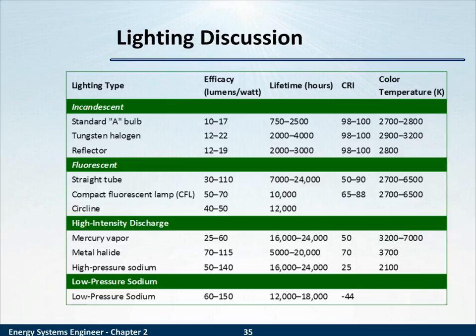Again, strength, like fluorescent, can be long life and high efficacy. Weakness, although you can have strong color temperature, its color rendering is not as good. And low pressure sodium, efficacy and lifetime, you saw it on the previous chart, is good. Color rendering index, look, we're not even between 0 and 100 anymore. Why is that? Because the weakness of low pressure sodium is its monochromatic yellow.